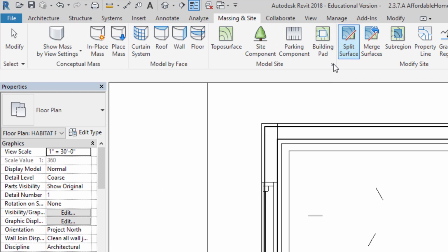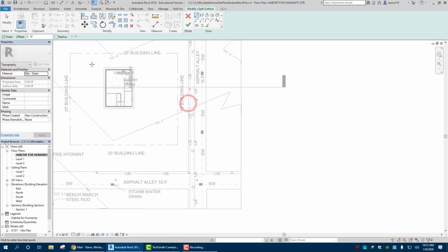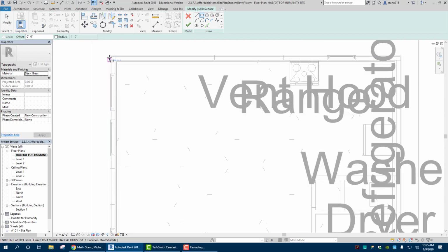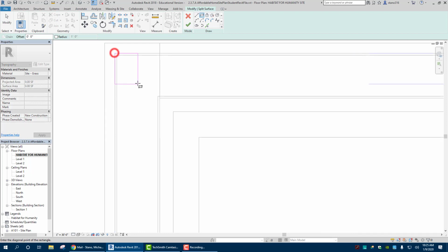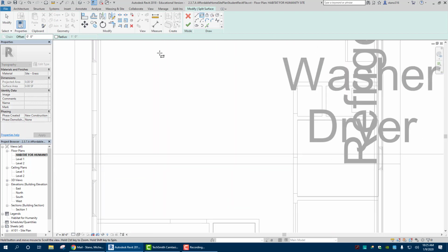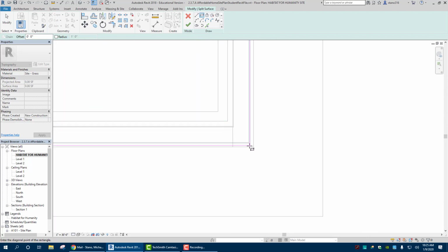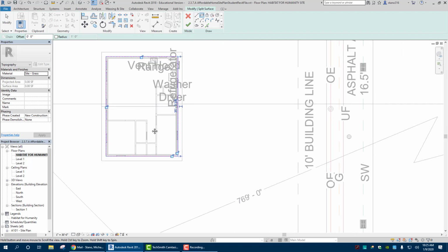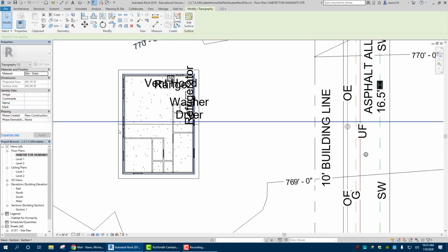When you do this, you have to zoom out, find the surface right there on the edge. I'm going to come in with the rectangle tool. You could draw this with individual lines, but I'm just going to go to the outside edge of the house. So now here is my foundation line. I'm going to zoom in, get there, and move all the way over to the other exterior foundation line right there. It's all good. I'm not going to bother locking it into place. It's fine. I'm not moving my house at this point. Finish it, edit. Now that surface is different.